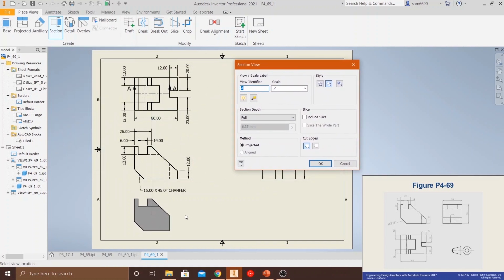There we go. You got to move it before you click OK. I mean, you can move it after, but it might just be complicated with all of the things. And you'll be able to move this around. It's going to stay in line with your view. So this will show you the cutting plane directions, what it looks like. If the arrow is up, that's how the cutting plane is cut. Down, it's cut in the other direction. Because we have other stuff in the area, it's kind of hard to see, but you would pull it down.